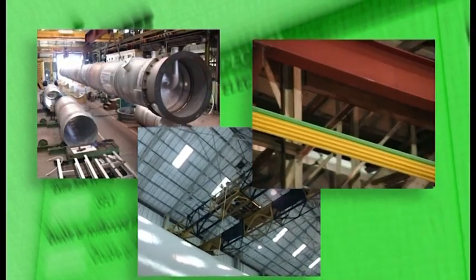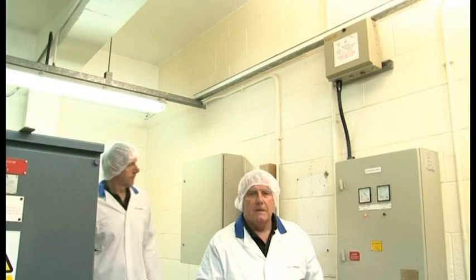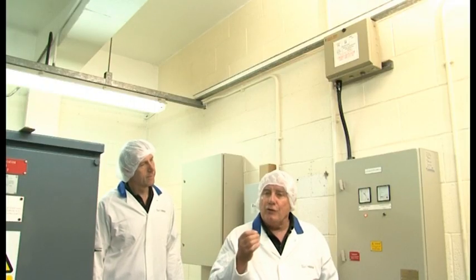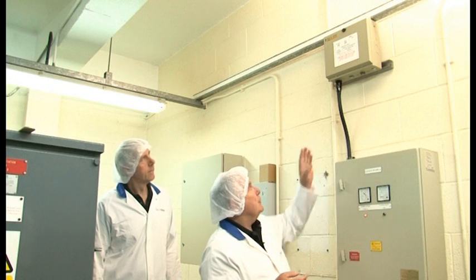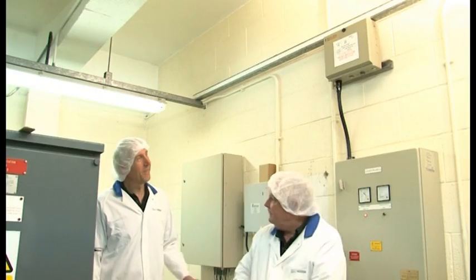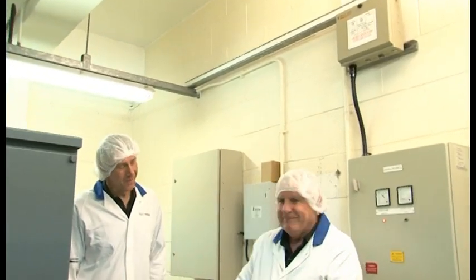A common example of by placing out of reach would be the exposed conductors supplying an overhead travelling crane. I've actually seen this box ticked on the schedule because the electrician mistakenly thought a consumer unit or a distribution board mounted at high level was an example of placing out of reach. Have you seen examples of obstacles? Obstacles is not so common.